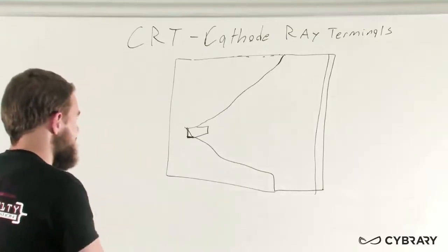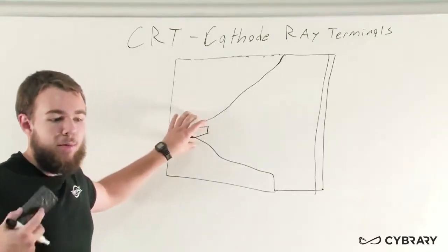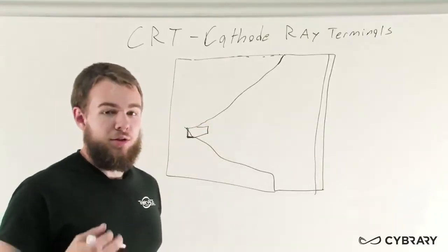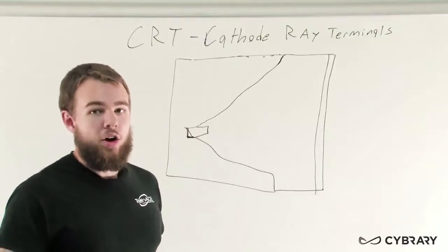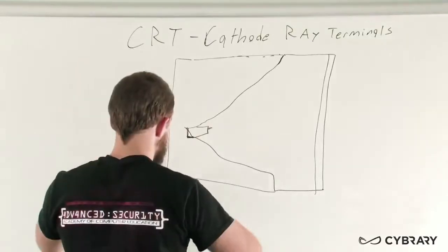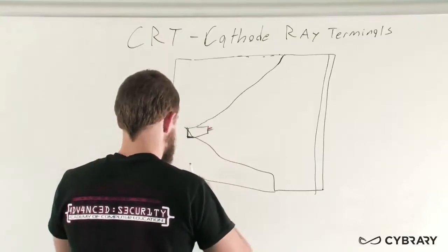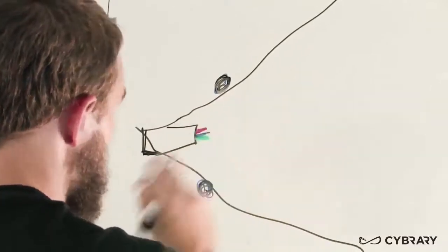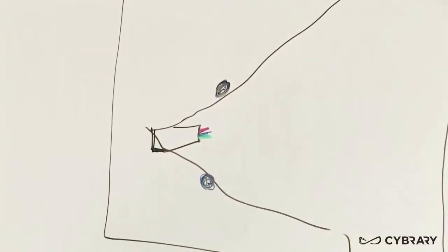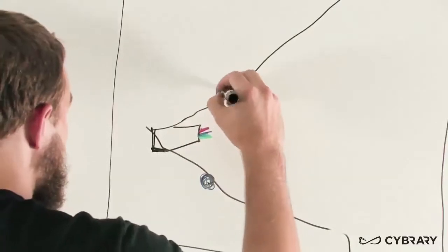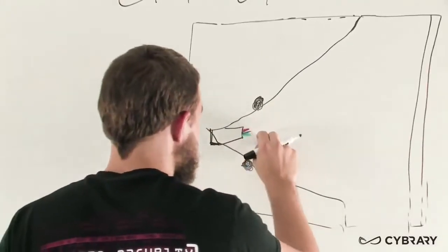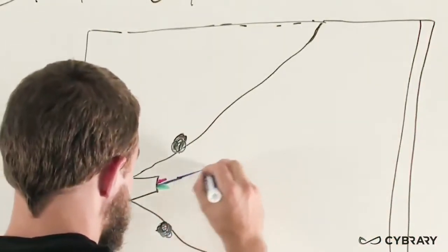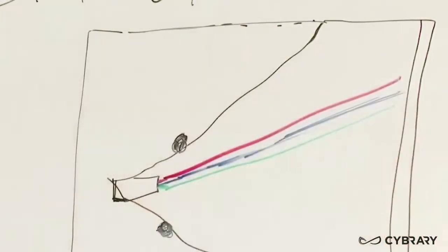But these electron beams are here in the back, and they shoot red, green, and blue electron beams. Commonly, you'll hear we have video screens that display video in RGB, or red, green, blue. And so that's what we have: the red, green, and blue. These red, green, and blue electron beams pass through an area with coils that are actually known as deflector coils. These deflector coils move and angle these beams against our screen, and these beams sweep across our screens, shooting the electron beams at them. And that's how we get our picture.